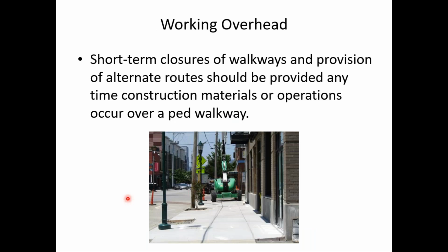Working overhead, sometimes that happens, right? Work takes place overhead, especially in downtown or business districts where you have multi-story buildings. So short-term closure of walkways and providing alternate routes needs to be provided anytime there's construction materials or operations over a walkway. Or in this case, you can see there's operation over the walkway, or there will be.